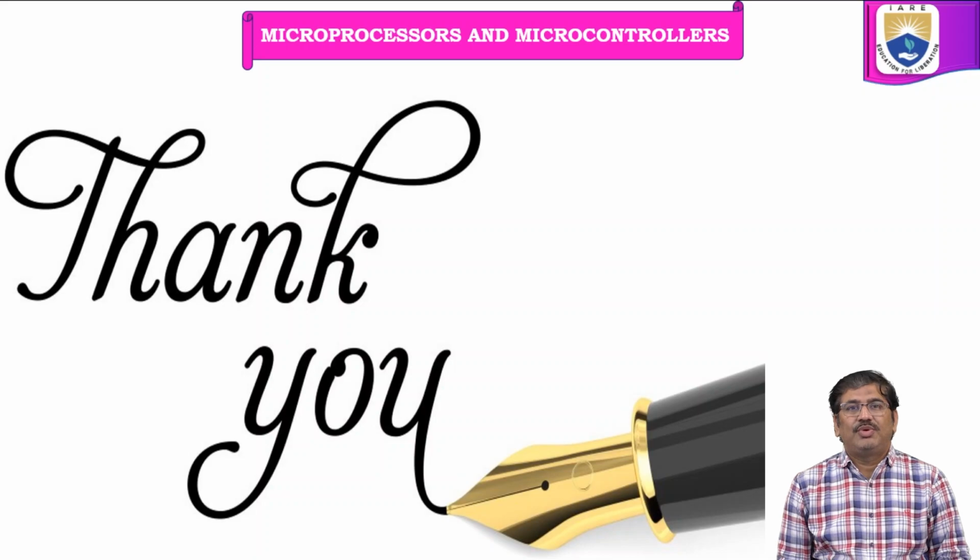The next ones correspond to bit checking followed by a jump with conditional checking, like JB, jump if bit set, and JNB, jump if bit not set. The next one is JBC, jump if bit set, and before going to the relative address, clear the particular bit. So these are the various instructions studied in this session, which correspond to the branch or control transfer instructions in the 8051 microcontroller.